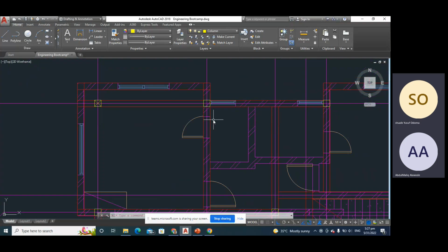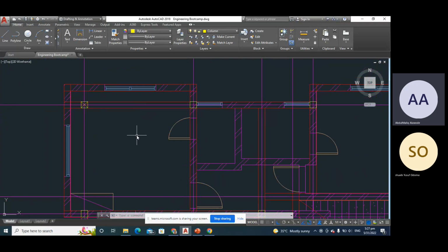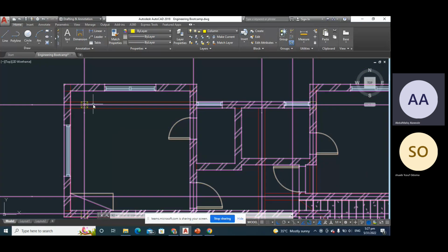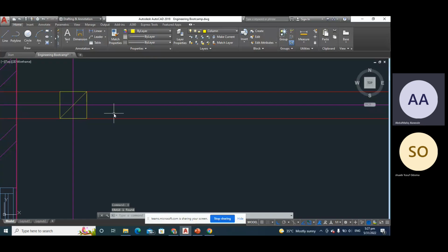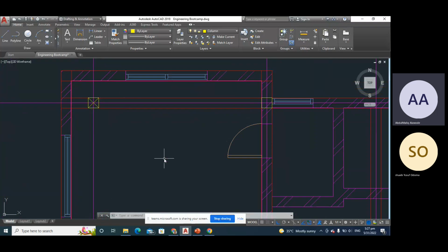Yes. It means in some other drawings, it exists below, but not an extension. It does not go beyond the floor under that level. You understand? Although you might have some drawing that will not use this sign. They might use another sign. But the most important thing is when you have your general drawing and you have signs, you should check around for the legend. So when we are done with our own structural layout too, we are going to prepare our legends to represent that.